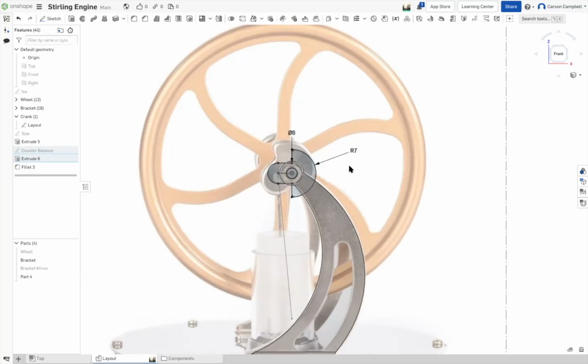But anyway, sheet metal part, what's the last feature in a printed part? Not a printed part, an injection molded part. What's the last feature in an injection molded part? They size it over 2% for shrinkage. It's not that magical.